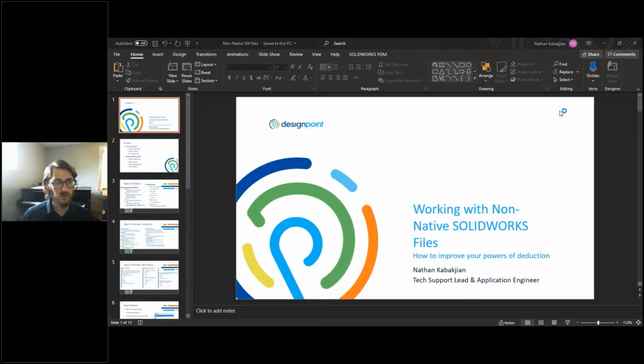We'll pull out Creo as the best case scenario. It imports and exports parts and assemblies, it's good at translating that information, not as good at translating any of their drawing information. Import body data, feature data, and mate data, excuse me. Again, it's good at reading that information, but there's other things like material selection, and so on and so forth, that it's not necessarily going to pull through. So you're never looking at a one-for-one scenario where all of your data is going to pull through perfectly.